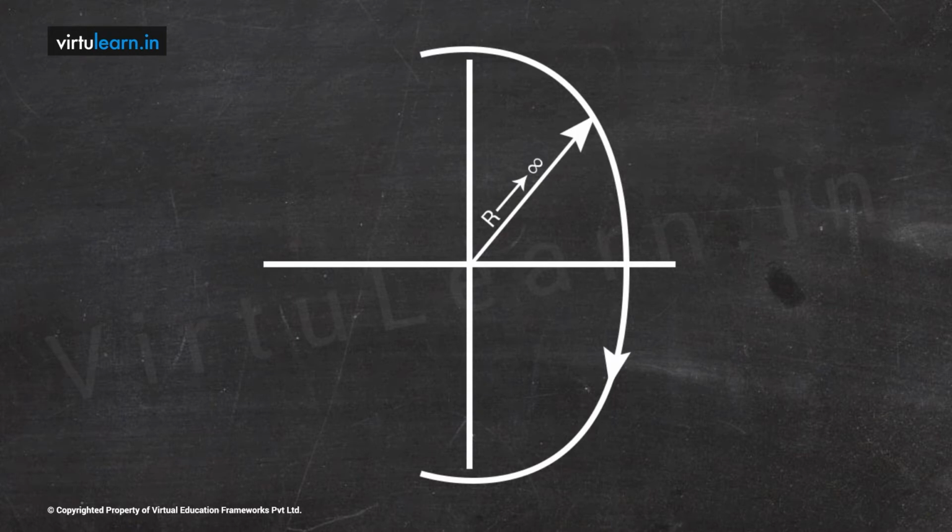When you map path 4 into the GH plane, you have to remember certain things. The first one is, how many poles do we have at the origin? We have one pole. Therefore, the resultant will have only one semicircle. And what will be the starting point of the semicircle? The starting point of the semicircle is the ending point of the inverse polar plot.